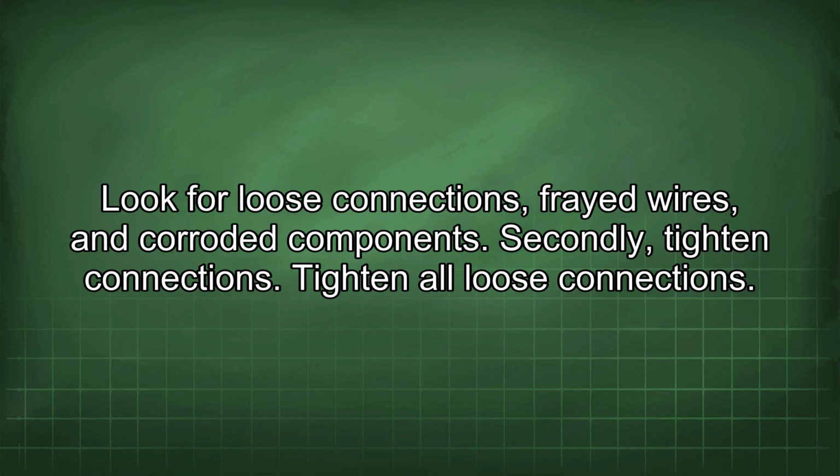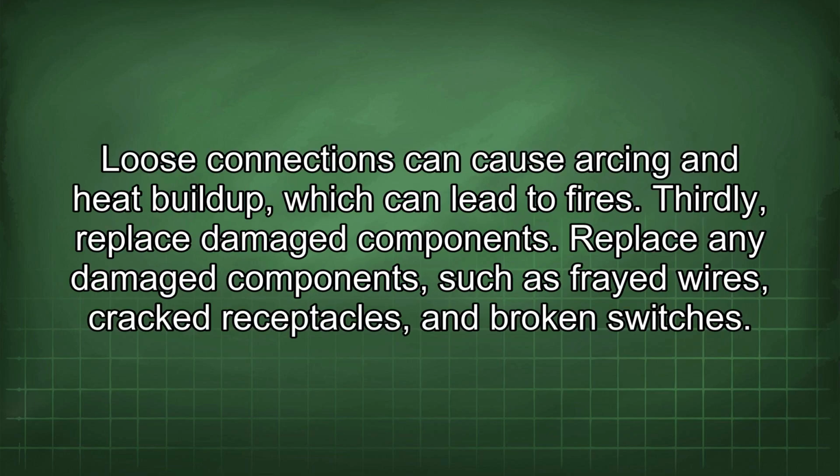Secondly, tighten connections. Tighten all loose connections. Loose connections can cause arcing and heat buildup, which can lead to fires. Thirdly, replace damaged components. Replace any damaged components, such as frayed wires, cracked receptacles, and broken switches.